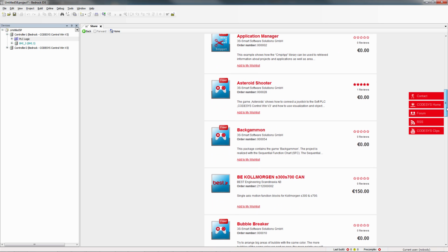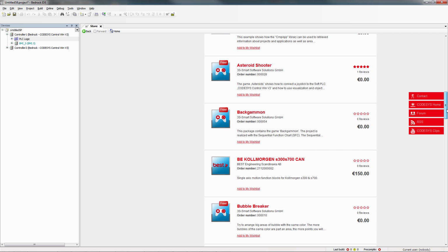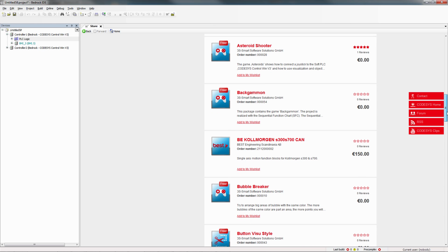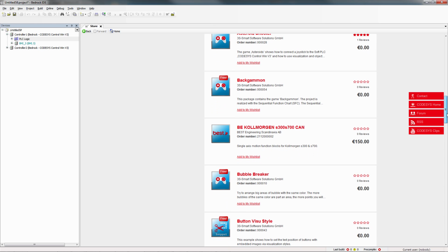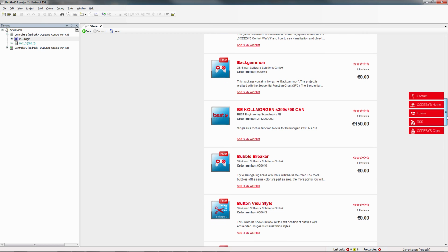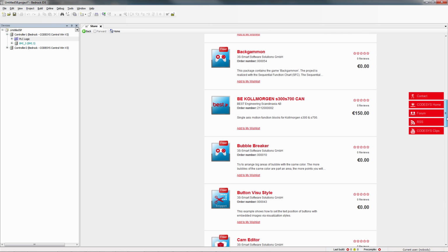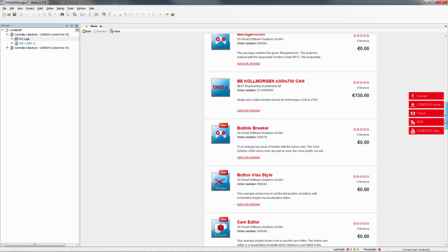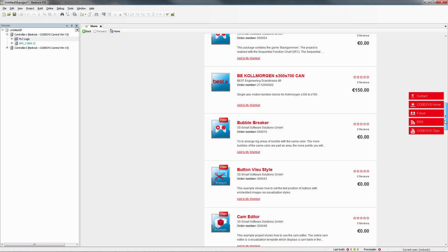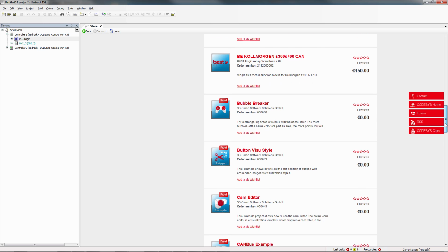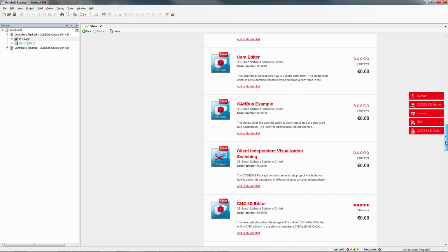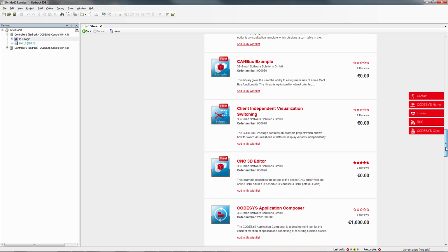It has quite a large number of libraries. It has file utilities for reading and writing files on the controller non-volatile RAM. It has matrix libraries with matrix inversion. It has an OMAC PACML state machine. It has date and time libraries. It has libraries for accessing CSV, XML, and INI files, again, on the controller non-volatile RAM.